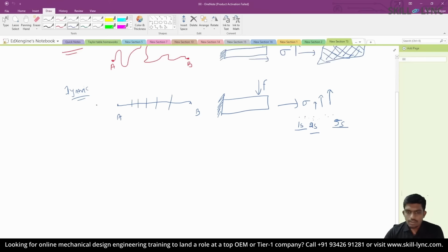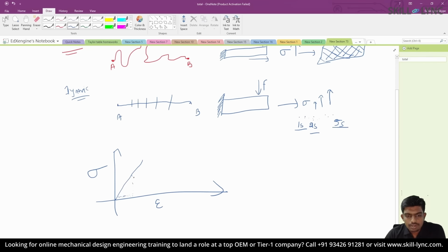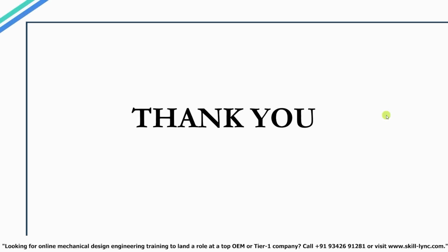That's because if you consider the stress strain graph, if the relation between the stress and strain is linear, you can see the displacement gets larger as the stress value increases, and when it enters a nonlinear region, as the displacement increases, the stress value doesn't increase that much. Hence, in the static analysis, our solver followed this extrapolated path such that for any value of load that we give, it received the corresponding stress and strain by just extrapolating this curve.